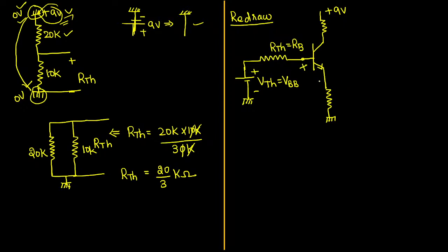And you know this is the base to emitter voltage. This voltage is always 0.7. Practically it is fixed, that is a silicon diode. And how am I fixing the polarity? See there, the direction of the current across the emitter terminal is going outside. It means the given transistor is an NPN transistor. In case of an NPN transistor, you know the direction of the diode. The diode will be fixed like this. This is going to be the anode, the opposite will be the cathode. Anode is positive, cathode is negative, a PN junction diode. Whereas for the PNP transistor, this case will be reversed.